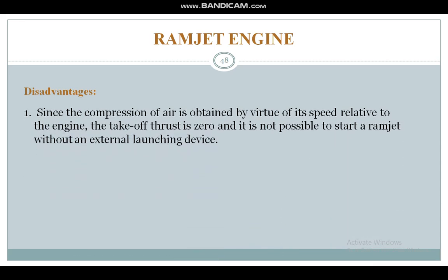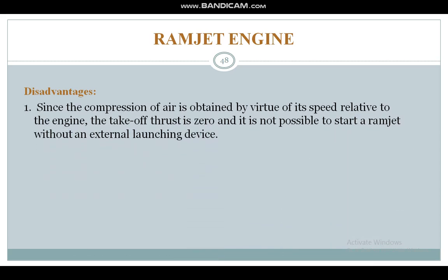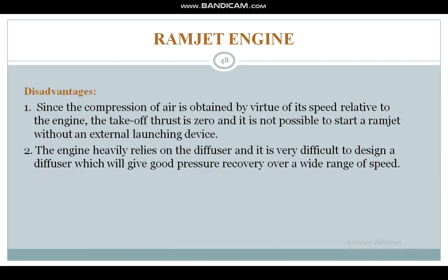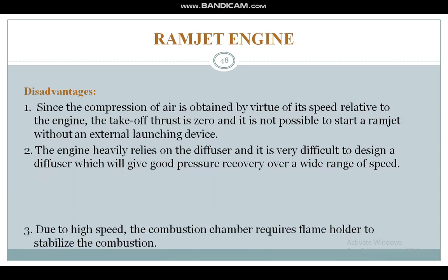But there are some disadvantages also. Since the compression of air is obtained by virtue of its speed relative to the engine, the takeoff thrust is zero and it is not possible to start a ramjet without an external launching device. The engine heavily relies on the diffuser and it is very difficult to design a diffuser which will give very good pressure recovery over a wide range of speeds.